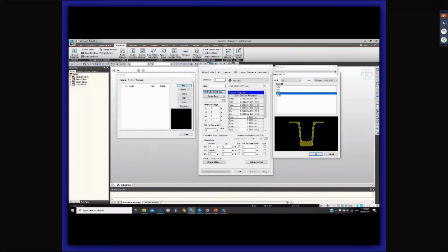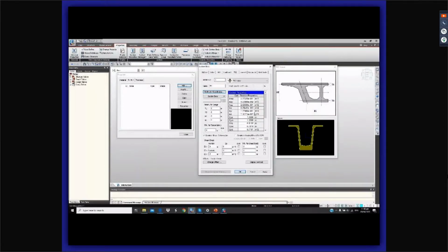So let's get the one with T4 and click on OK. Next, the parameters for design. We need to define the thickness of the top flange, the thickness of the bottom flange, the width, and then the effective height. For the thickness of the bottom flange, 260 mm. The width, 0.58. And for the effective height, 1.3333 meters. Then for the thickness of the web, we input 120.